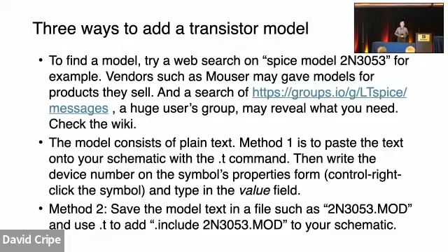But we use a lot of stuff that's 20 or 30 or 60 years out of date, but all that stuff's still out there. You're just not going to the vendor. You're going to other hams, you go into the LTspice users group, and there are huge databases out there. And when you find one, don't just take that one. Take the whole thing. If somebody's got 500 old transistors, take the whole database. Build up your own library.